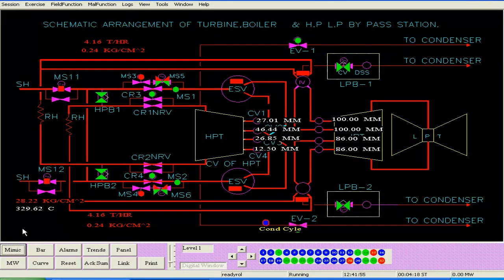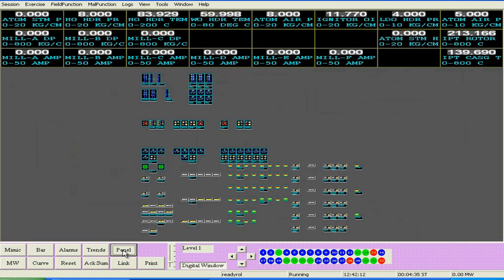The speed raising is a little bit slower, because we want to raise the speed at a rate of around 50 rpm per minute. So it will take around 10 minutes, or maybe 7 to 8 minutes, to get to the full 500 rpm.